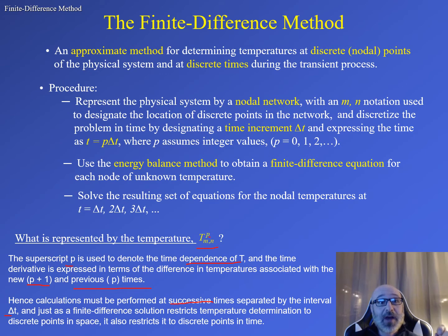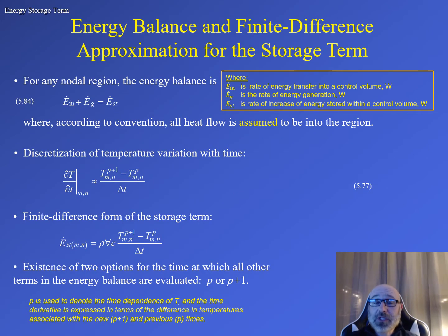And just as a finite difference solution restricts temperature determination to discrete points in space, it also restricts it to discrete points in time as well. So as we were looking through that procedure that we wrote up on the previous slide, one thing that we noticed is that there was an energy balance equation we need to deal with there. So now for our energy storage term, let's take a look at this energy balance and our finite difference approximation for the storage term right there.